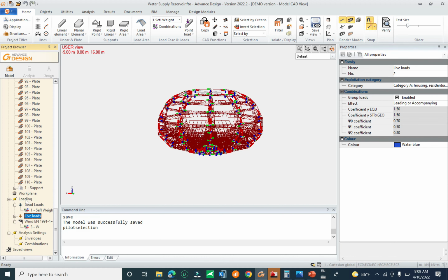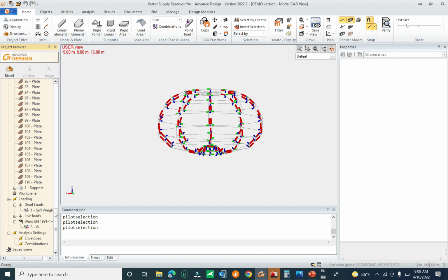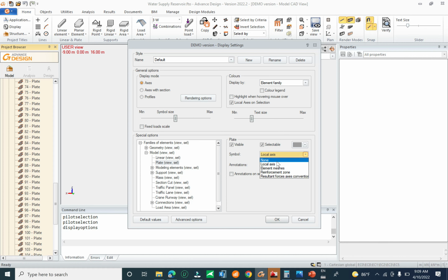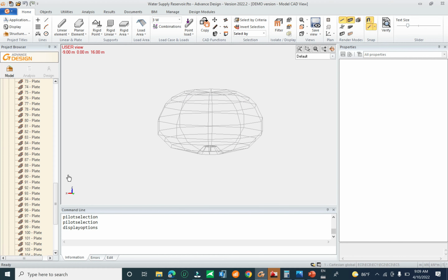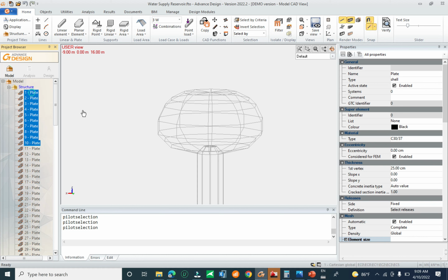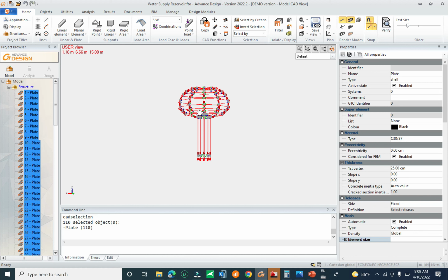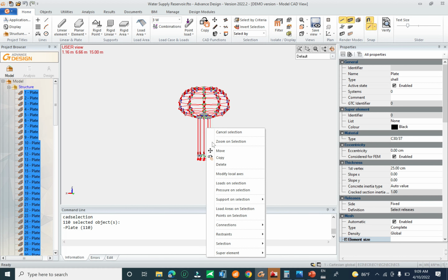After you complete these two types of load, you can turn them off by clicking on the line load and taking the quality off, and double click on the structure again, or you can shift click. Select all loads, select all cells, right click and click reload.